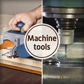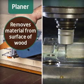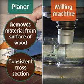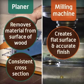Shaping of material can also be done using machine tools such as lathes, grinding machines, milling machines, and planers. A planer or thicknesser is used to remove material from the surface of wood to give a consistent cross-section, which is difficult by hand. A milling machine is similar, removing a thin layer of material at a time, allowing the operator to create the required size or shape. It also makes the surface flat and gives an accurate finish.